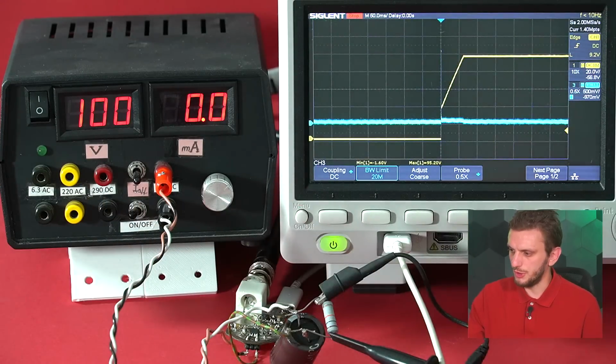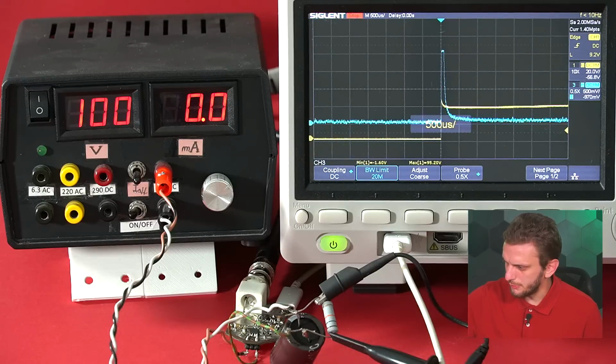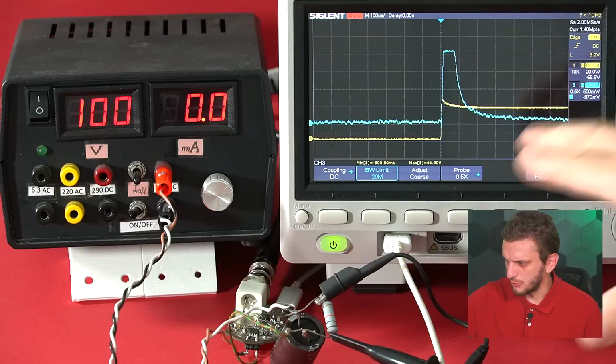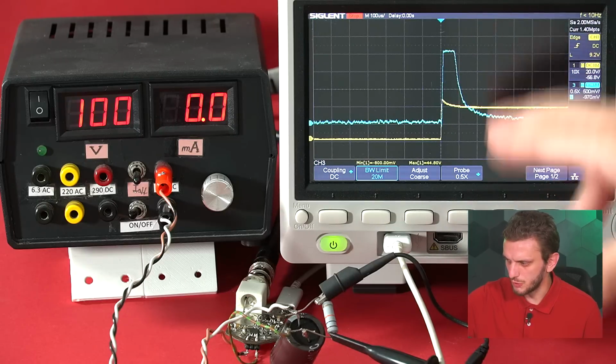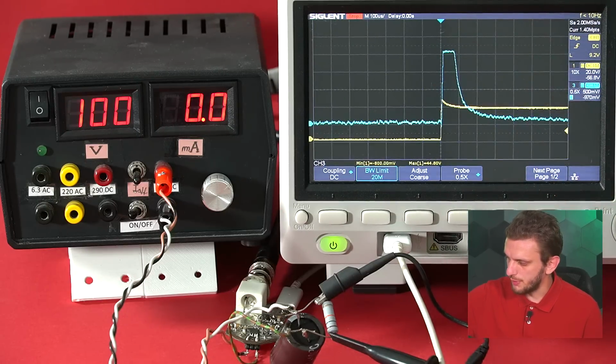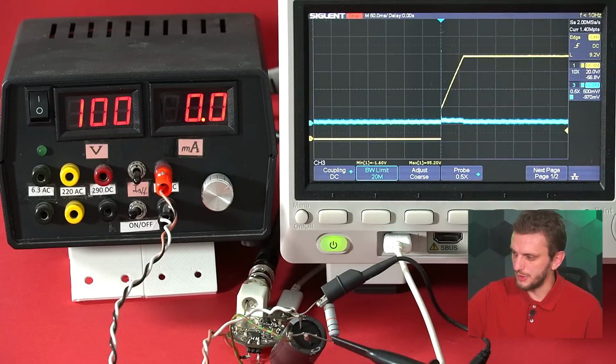When the voltage gets activated, when it's connected to the capacitor, we see a small spike. If we zoom in a bit, we see that the current jumps to quite a high value. We have about 2.5 amperes here, so it's 500 milliamperes per division, after which the current drops to a smaller value, and the voltage then slowly increases.